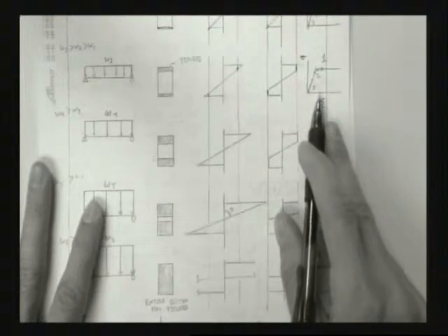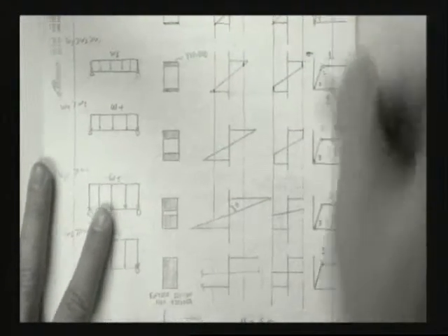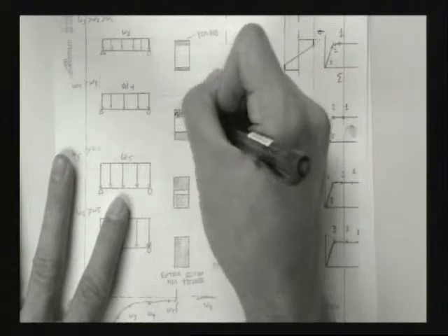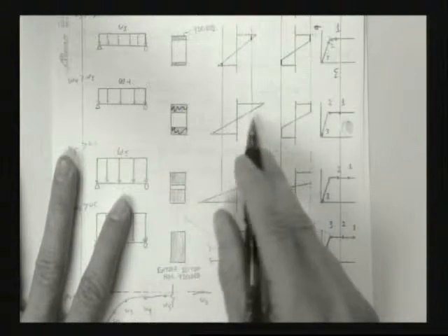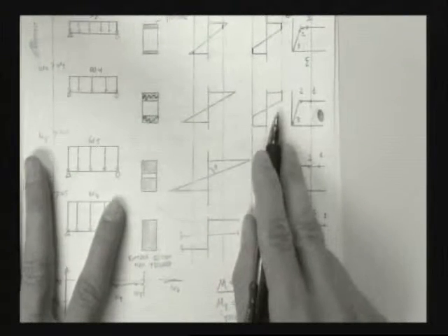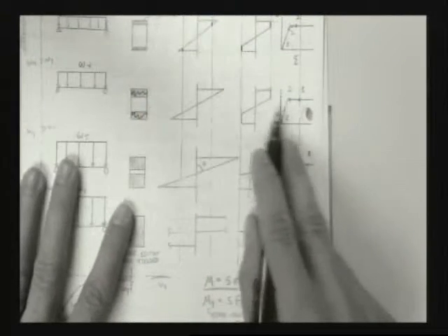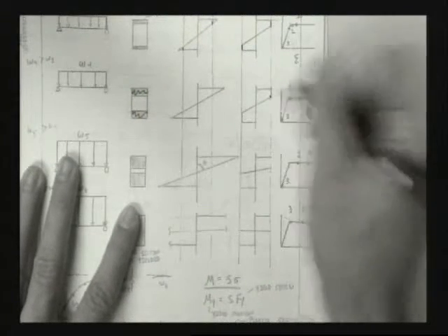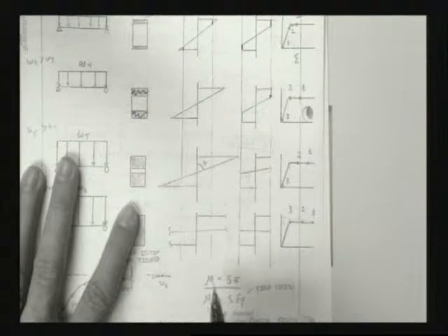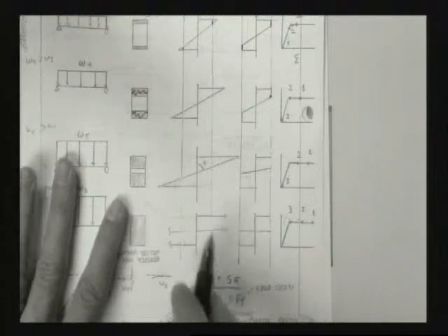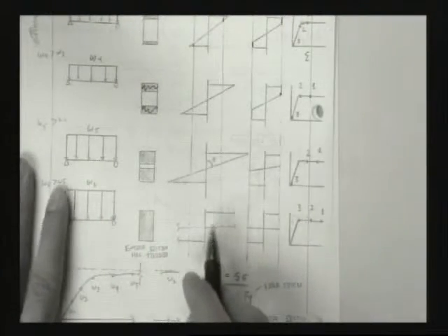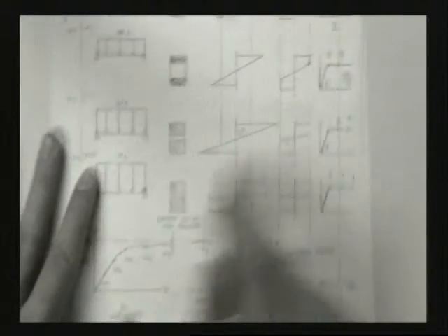So as they keep increasing the load, we get more of it yielded. More of the cross section is above yield strain. More of the cross section is at its yield stress. So much so that point 2 has now reached its yield. But life again is not over. It's stressful, but it's not over. We can keep increasing loads.